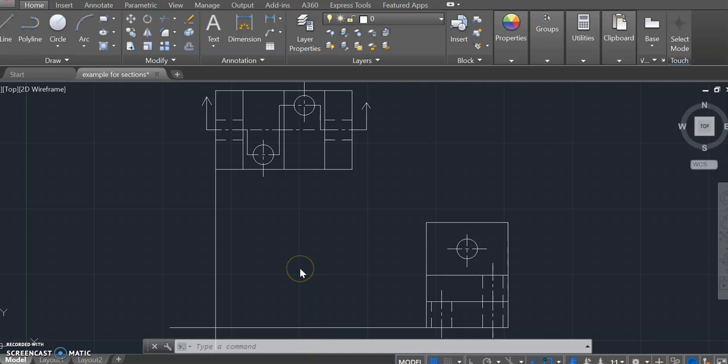Okay, what we're going to do today is I'm going to show you guys an example of how you can draw a section. Specifically, we're going to work on an offset section. If you take a look at the views that I have right now, minus these two lines that are here, these are some projection lines that I've drawn to get my section view started. My section is going to be taking through these steps right here that I'm outlining with my mouse. Okay, and it's going to be looking in that direction. That's why this section view has to be down in this area.